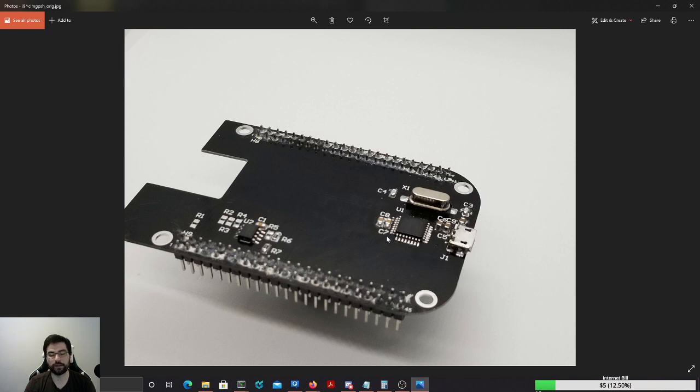It's a bad design, but the interesting thing is this is a USB device controller, and it's 2 layers, and it's a little bit complicated, but differential signaling on a 2-layer board can be really tricky if you need to maintain a particular impedance, because the distance between the top and the bottom layer is so far and you can't adjust it. So what I did here is I just made the board super duper thin, and actually I have some, I think. Let me just grab one. Because you can see when I pull one out that they just kind of wobble, wobble, wobble.